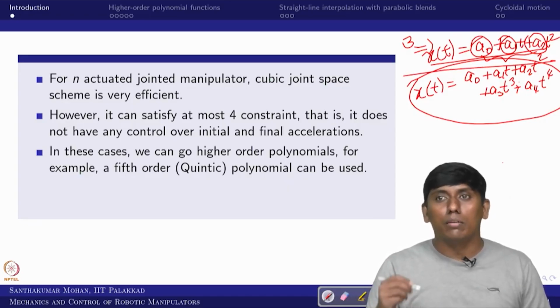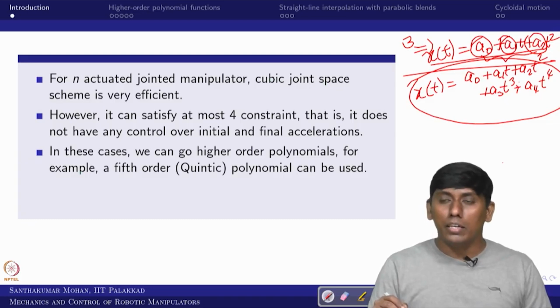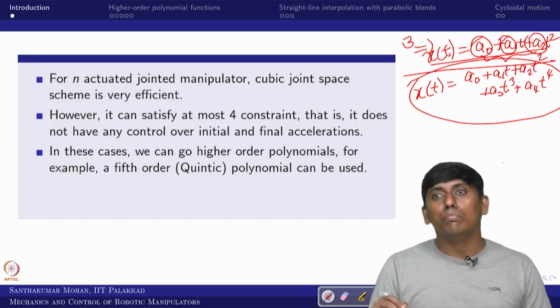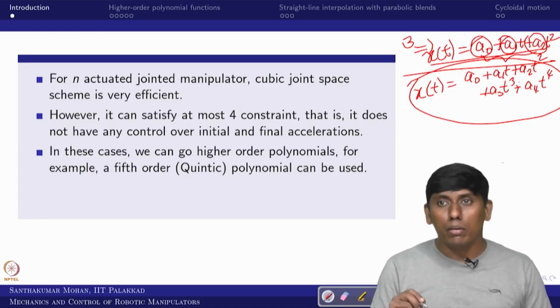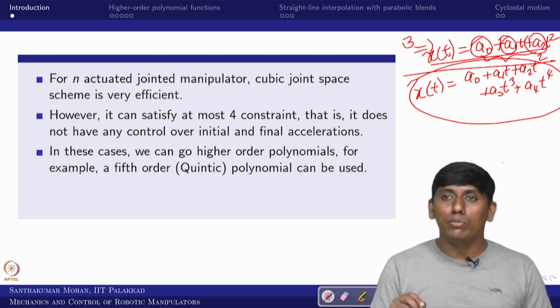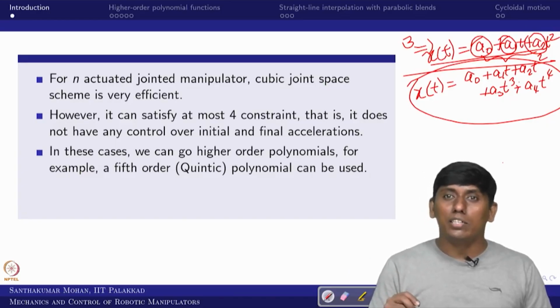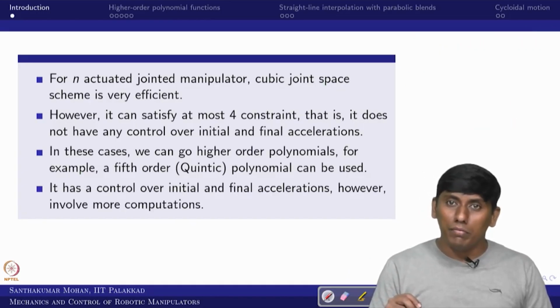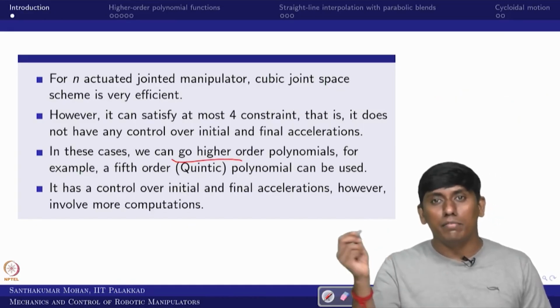Initial velocity they will not bother about, usually the initial velocity also starts from 0, but fourth order or sixth order is not straightforward. Further, the coefficients can be prone to make the values unstable. But if you use odd orders of polynomial, the number of unknowns and number of equations are equal, in the sense of an even number, and the equations are stable. That is the whole idea. That is why we use higher order polynomials like fifth or seventh, so third, 5, 7 like that.